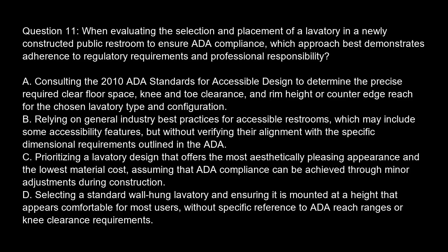Question 11. When evaluating the selection and placement of a lavatory in a newly constructed public restroom to ensure ADA compliance, which approach best demonstrates adherence to regulatory requirements and professional responsibility? Option A. Consulting the 2010 ADA standards for accessible design to determine the precise required clear floor space, knee and toe clearance, and rim height or counter edge reach for the chosen lavatory type and configuration.